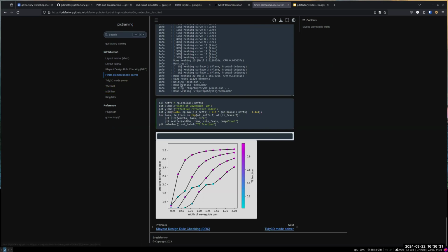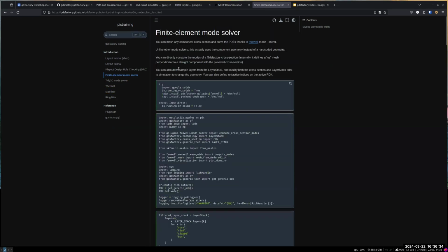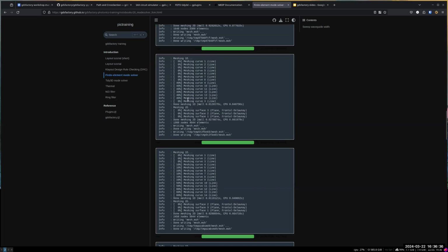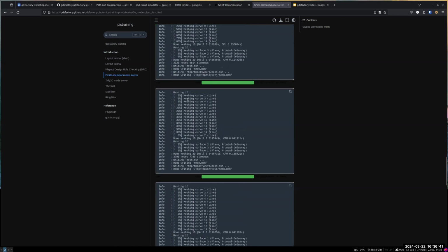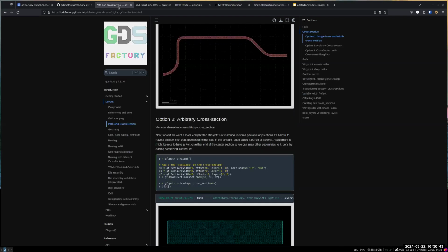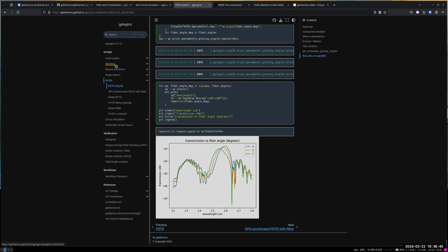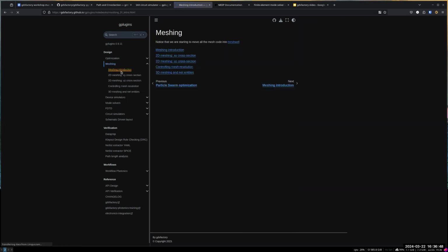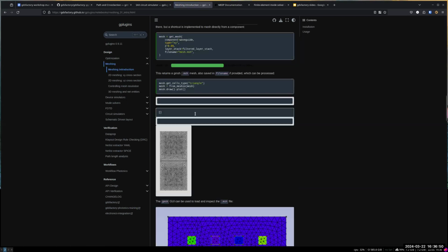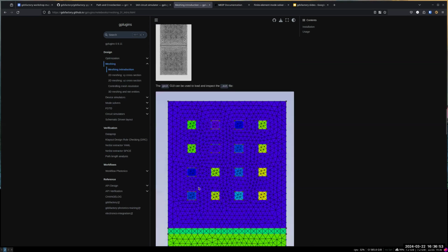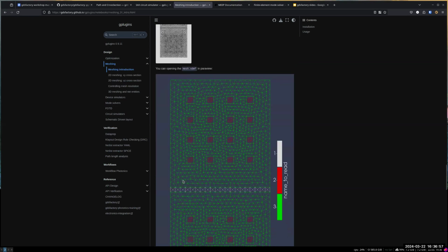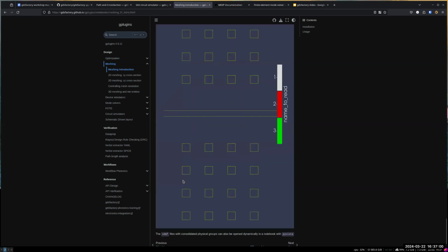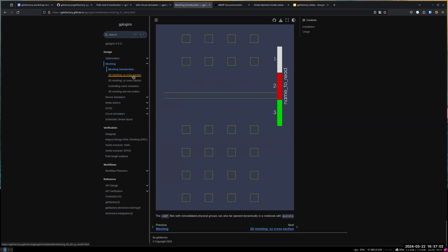And we're going to use two types. We're going to use the finite element. Maybe we should show the mesh in the tutorial. If you go to the plugins, we have another example of meshing that explains how the meshing of an FEM example works. A mesh divides your structure into small triangles, and you can adjust how fine you want the mesh to be. So you can do mesh refinement. So this is the FEM.